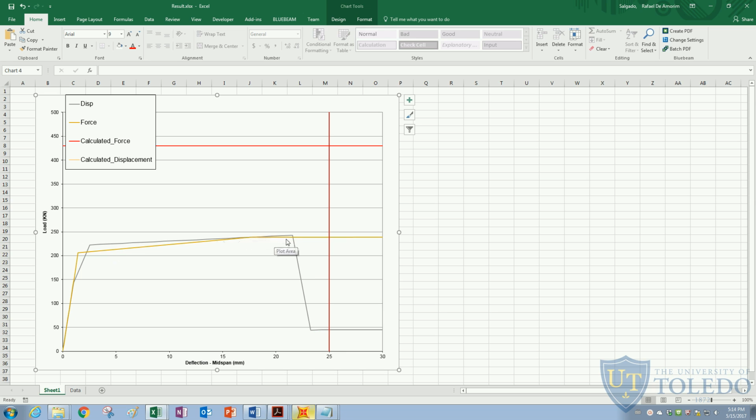What we can see here is that the gray one, once it reaches the peak force, it unloads to a residual force and then it goes to zero. Whereas the force-based analysis doesn't, and it goes indefinitely once the peak is reached. As we can see, the load capacity calculated by SAP2000 is about half the one we got by the code. A very highly conservative response by SAP2000.